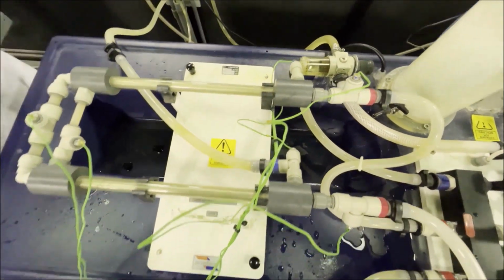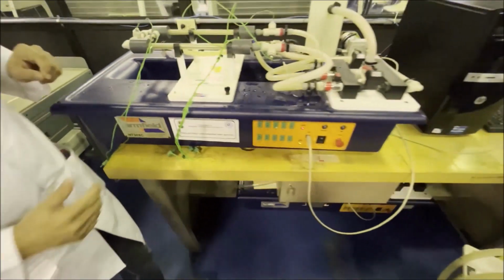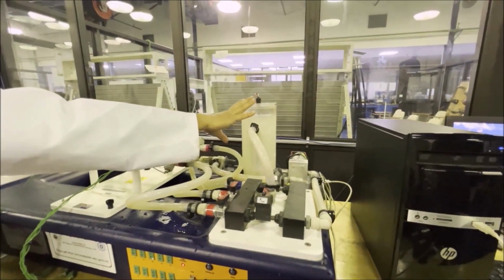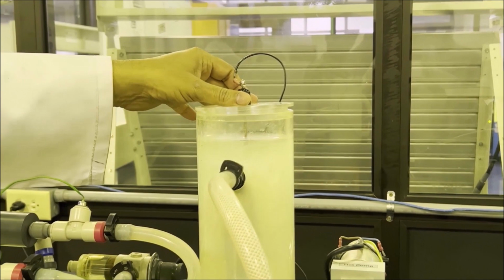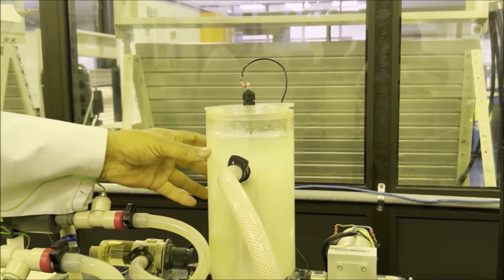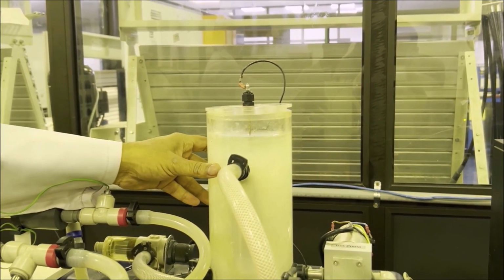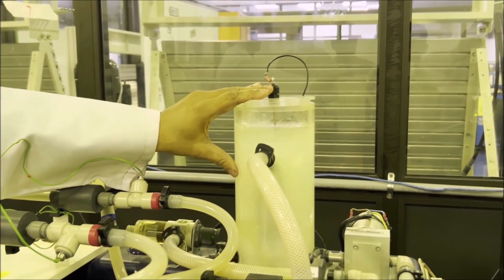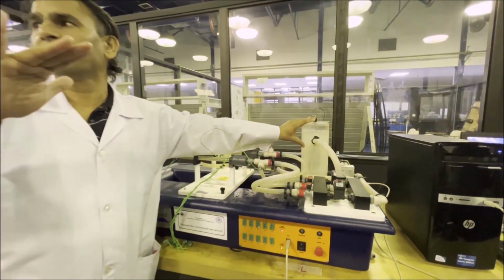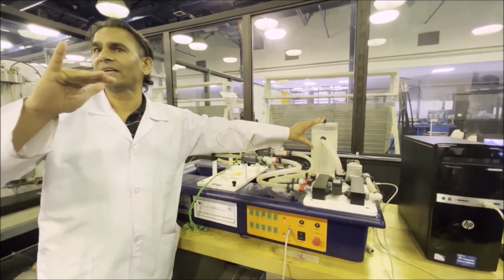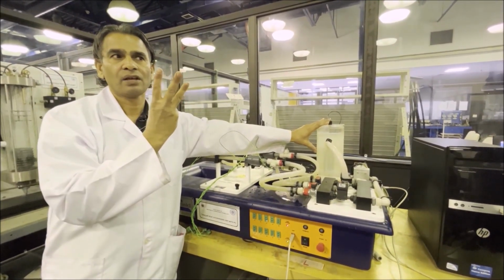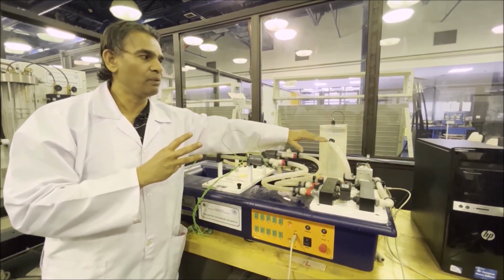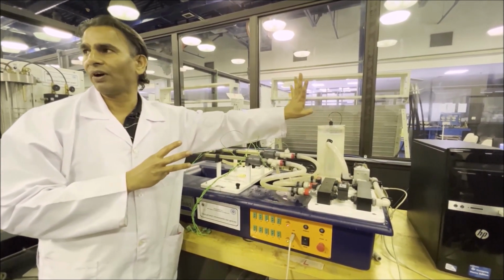Now hot water, how will it flow? So this is a tank. In the tank the water is heated. This is a temperature sensor. This is for control. If you want to heat this water up to 50 degrees, the water will be heated up to 50 degrees and the heater will switch off automatically. Maximum temperature is 50, 60. So we can set 3 readings: 45, 50, 55. The water will be heated up to that and it will switch off automatically.